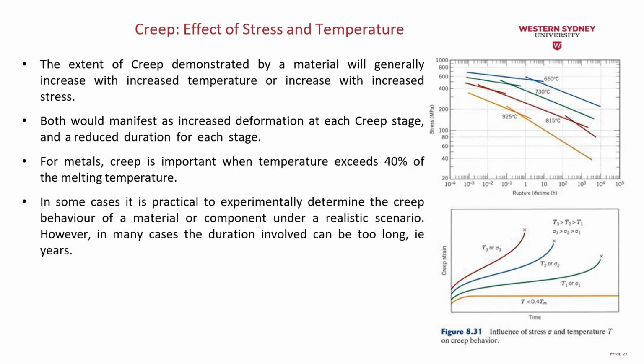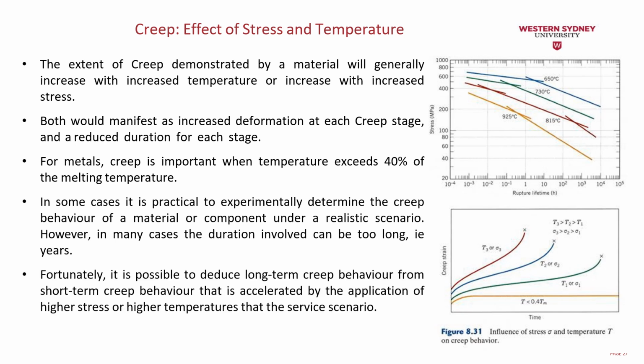In some cases, it is practical to experimentally determine the creep behavior of the materials or the components under the realistic scenario. However, in many cases, the duration involved can be too long, for example, 4 years. Fortunately, it is possible to predict the long-term creep behavior from the short-term creep behavior, accelerated by the application of higher stress or higher temperatures that can simulate this scenario.